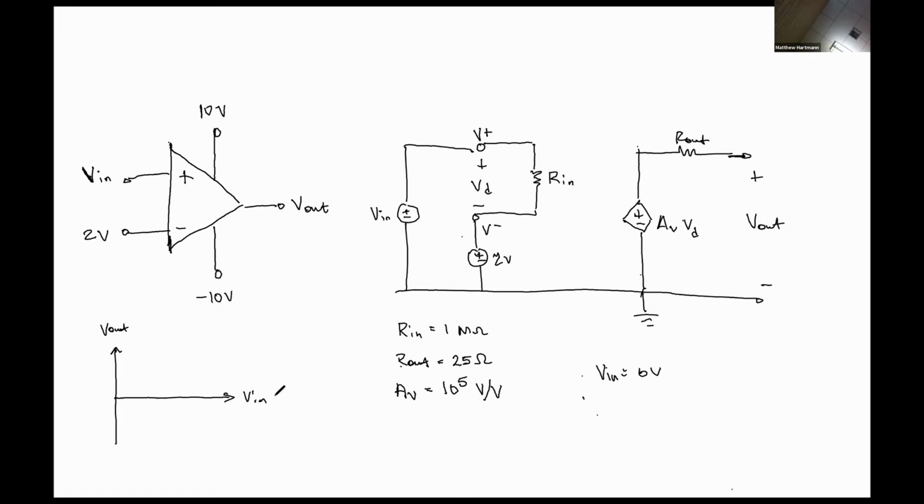Is the math correct? Let's start there. Yes. So it should be -200,000 volts, but if we apply the saturation distortion, meaning that we are limiting our output voltage, saying it can be no more negative than VCC minus, what is our actual output voltage going to be then? So VCC minus is this guy right here. Right, so we're going to saturate to that value.